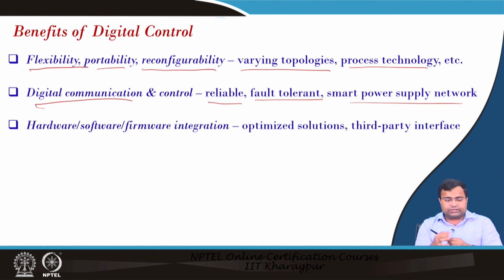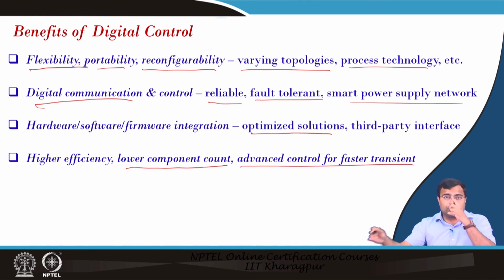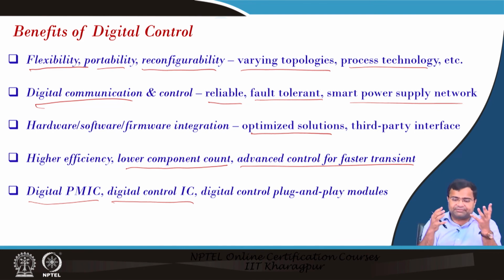And because of this digital solution, you can have hardware software firmware integration. So, you will get an optimized solution, and you can also interface third party solutions, and you can achieve high efficiency by playing with multi-mode solutions and lower component count, because all the components are inside the digital control IC. You can implement advanced control logic like digital nonlinear control, large signal based control to achieve very fast transient response along with small signal control. Then you can have a digital power management IC solution, or a digital control IC, for example in multi-phase which controls multiple phases, or a system level solution which can be a microcontroller for controlling PFC or LLC.